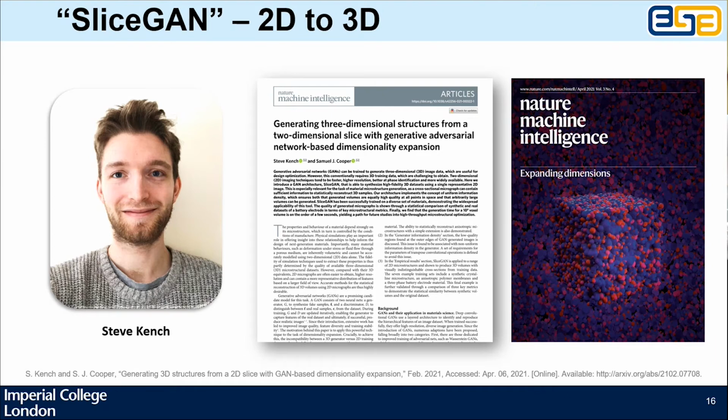And we think this has got some really important implications. There's a lot of neat maths in granular media that shows you that actually all the information that you'd need to know about a macro-homogeneous material will be present in a large enough two-dimensional image. And this means that we can use methods like the kintsugi method I showed you earlier with the platinum deposition, and just collect very large regions very quickly compared to setting up a computed tomography scan, and then use that as the basis of generating 3D volumes using SliceGAN, which is what we call the algorithm.